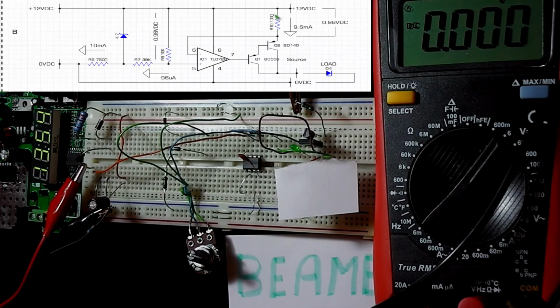So that's it. Finally, I'd like to add that with a current source, it's always worth bearing in mind that with a very large resistance, the voltage on the output will always be at the compliance voltage initially. This can be a bad thing if you're running semiconductors or circuits that require initially a low voltage that doesn't go to the compliance voltage.